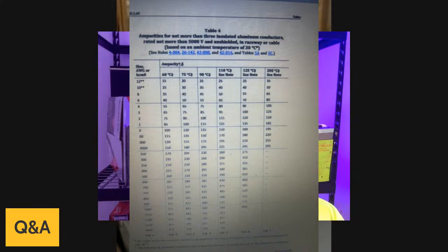It's going to show us, all the way on the left-hand side, 12 is your wire size, number 10, number 8, number 6. It shows you the ampacity, which is if you're going under 60 degrees Celsius. Normally, for 200 amp we will use from a 3 up to a 4 up.